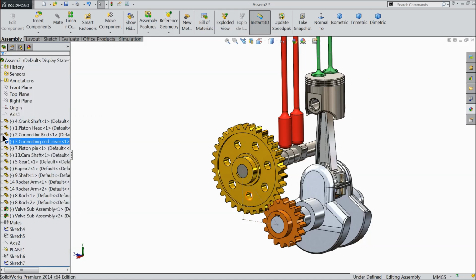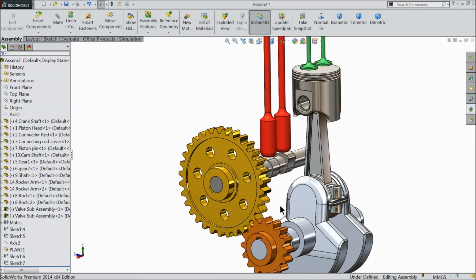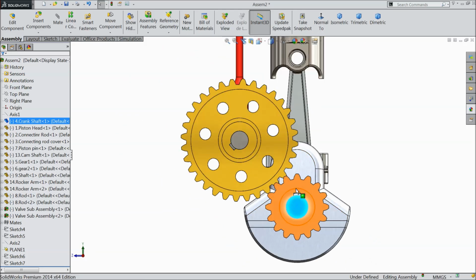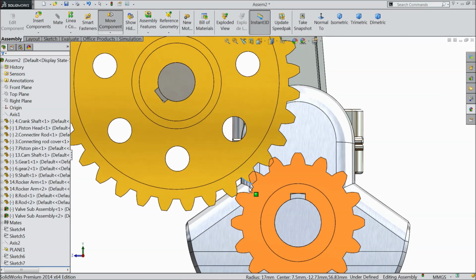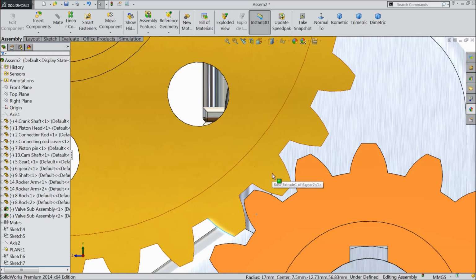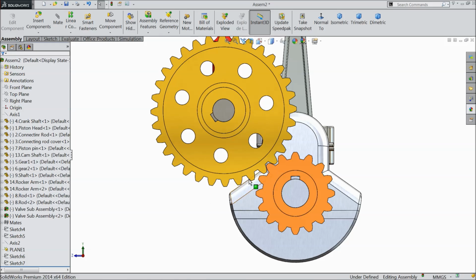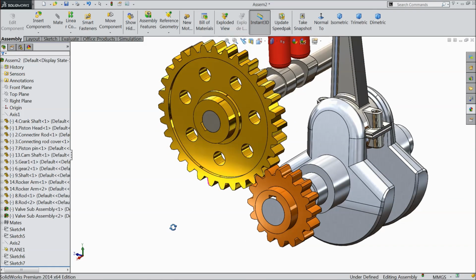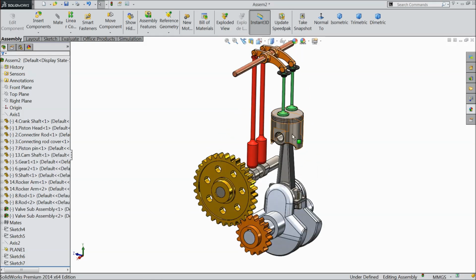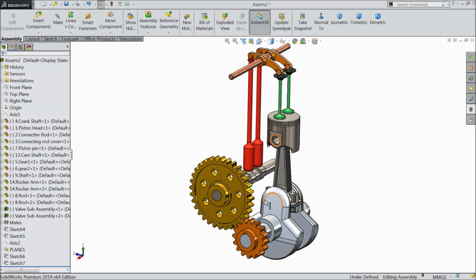Now hide all the geometry, hide the sketch, and the last sketch also hide, no need to show here. Select this face and see the front face and just change the gear, set the gear, because we are going to make a very important relation in the engine, gear relation. On behalf of this gear, it will run the whole engine.